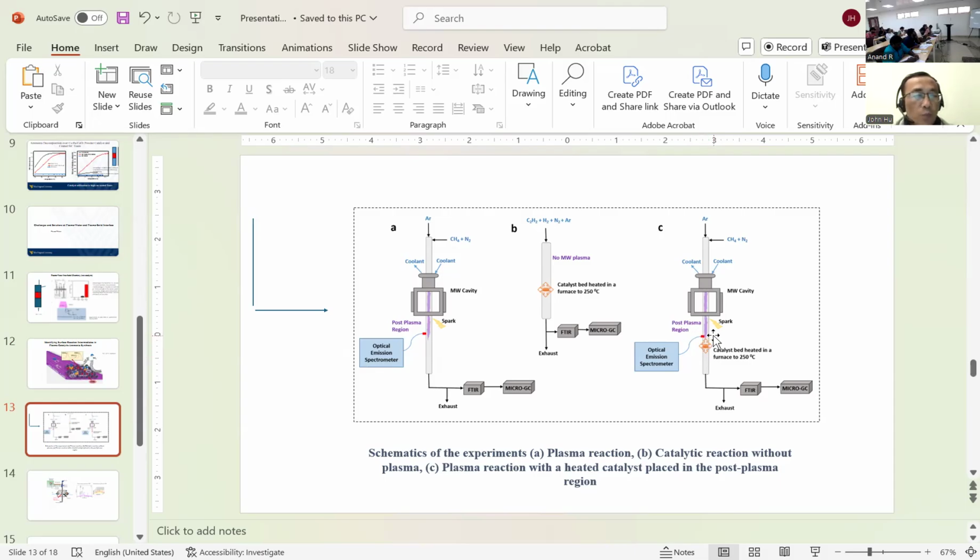I mean, if plasma reaches the surface. Sometimes plasma dies halfway. You don't even know, so it's very important. That's why I mentioned the other day, you need to have the optical, it's called OES, optical emission spectroscopy. It's not expensive. You can buy it easily. But we found out it's very important for plasma, microwave plasma detection.